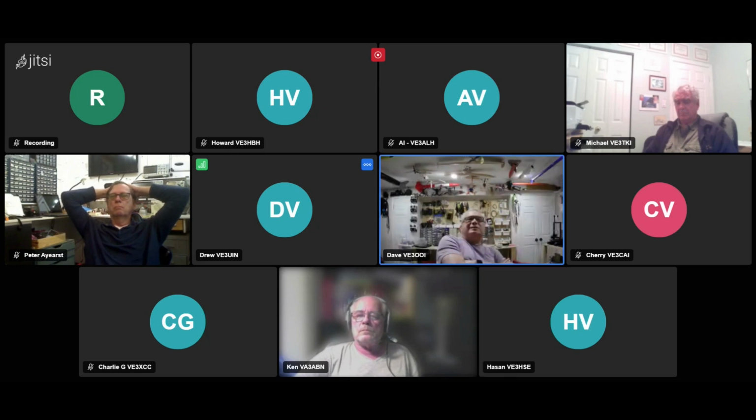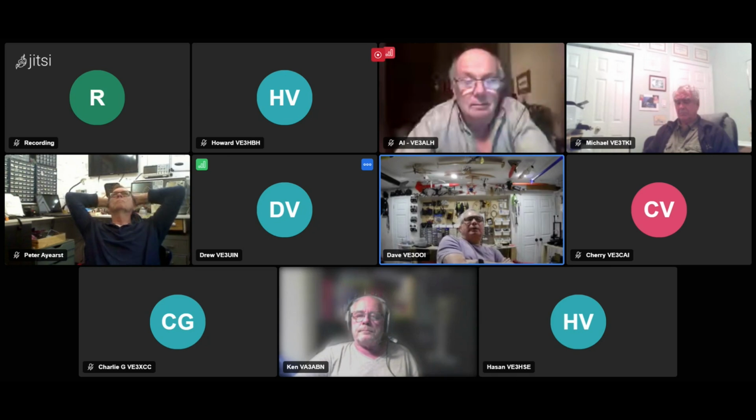No, that's where you take a calibrated noise source, you feed it into your device under test. It's got a well-known noise level, right? You know exactly what the noise is. It's like a calibrated signal source, but it's noise. It's generating white noise or shot noise or whatever type of noise.